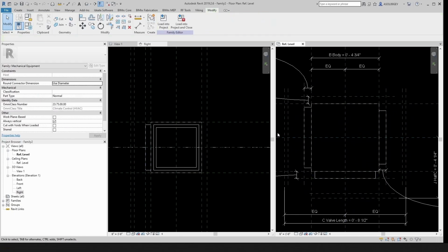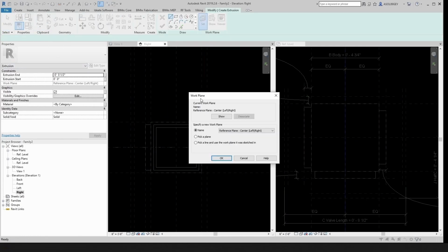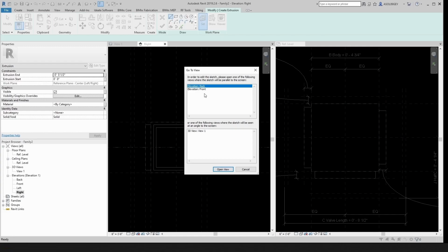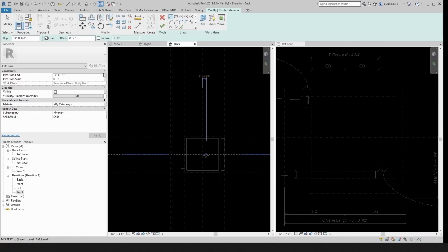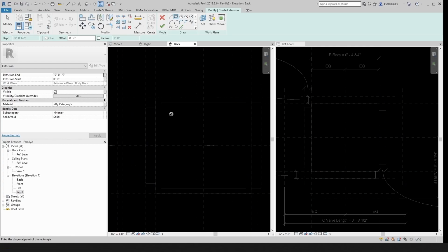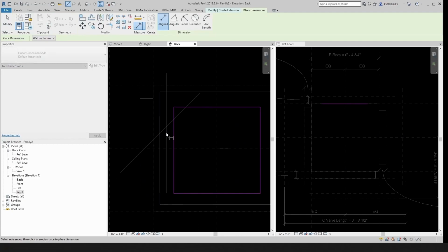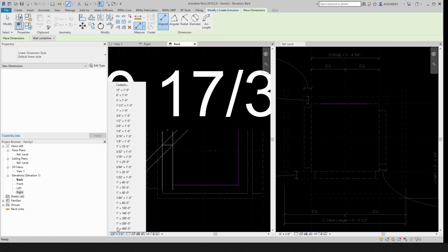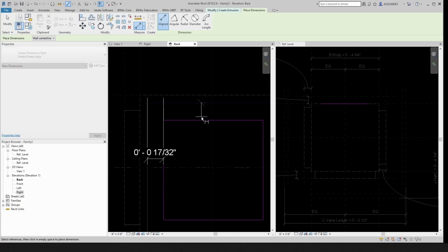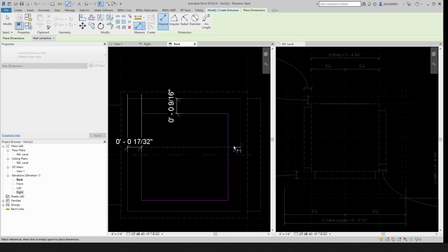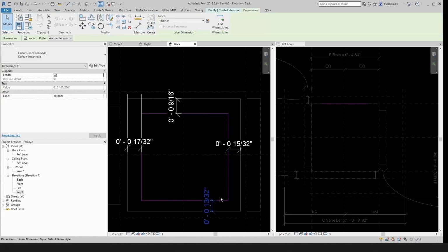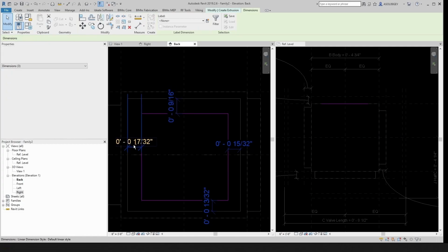So just one more extrusion in the back plane. So create, extrusion. We set our body back plane. Okay, let's go to the back. We create a rectangle. Same story. We're experts already on this. We just come here from strong to weak. And we know that we like it a little bit smaller. From here to here. Another one. Strong to weak.